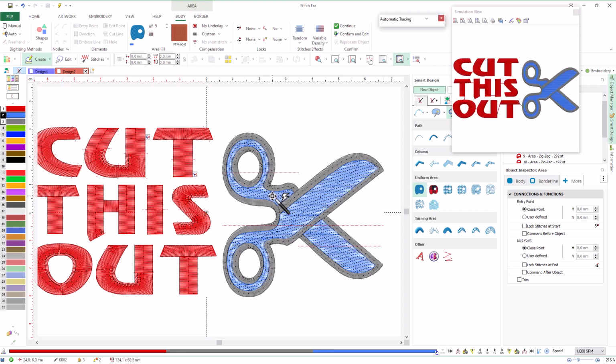If we review our design, we notice that we made a mistake in the sequence we followed to create the objects. We should have digitized the uniform areas of the scissors body first and then the edges. This is the usual way to do it since we get a much better finish. Let's adjust the sequence using the document map.